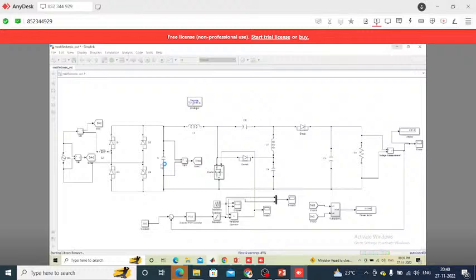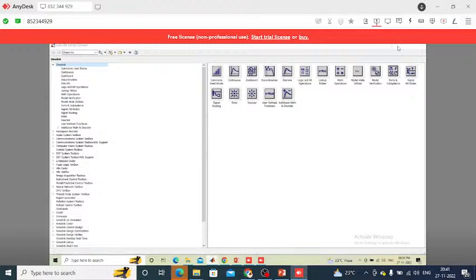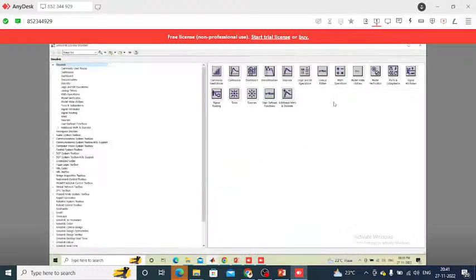While checking the output, it was connected to the go to block. After the go to block I connected an inductor. The value of the inductor is 75 e power of minus 3. Here two types of switches are available, MOSFET and IGBT. I took the MOSFET switch here.